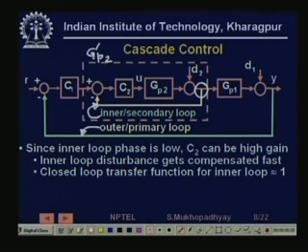So, if it has reduced, then the value of C1 can be increased, the gains of the controller can be increased, right. So, C2 can too. Which means that the overall transient response will improve, because any set point change in R will be acted upon much faster by C1 because it has higher gains. So, that is a very good advantage.